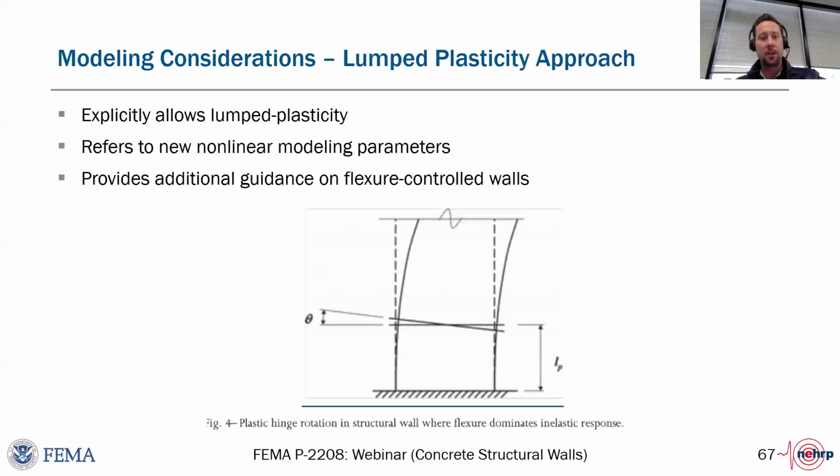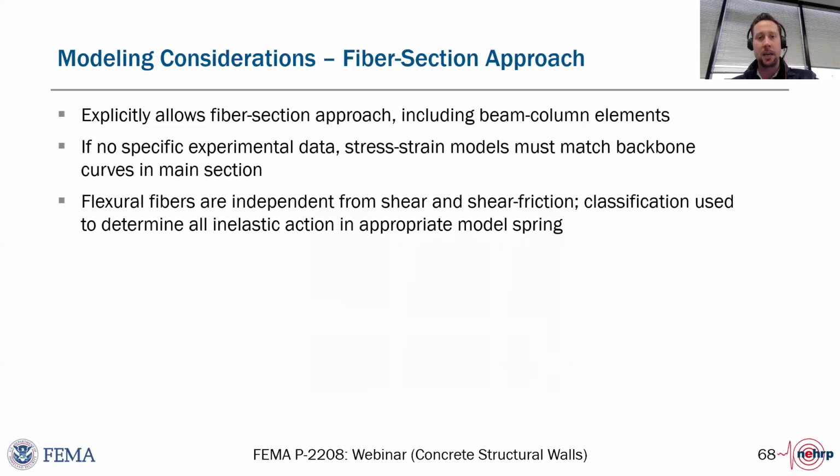The other key thing that I'll mention is that if you're using a fiber model, it's not as simple as just putting in a stress strain relationship for your fibers. You really need to consider your mesh and your global load deformation envelope, and whether that matches the recommended load deformation envelopes or backbones that come out of these recommendations, because there's a lot at play that's not only dependent on your fibers. There's shear flexure interaction, as I mentioned. There's mesh dependency in any continuum model. So this document offers some good guidance on how to consider some of that.